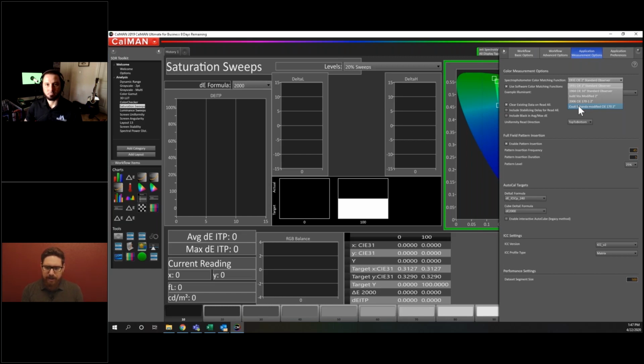One was CCFL based, one was white LED, one was PFS phosphor LED, and they still all look different, even using this color matching function, CIE 2015. So I still don't think that just another color matching function, it does make an improvement, but it's not something where if you just use this, they'll look perfect to everybody and all technologies will look the same. I don't think we're there yet for color matching functions.